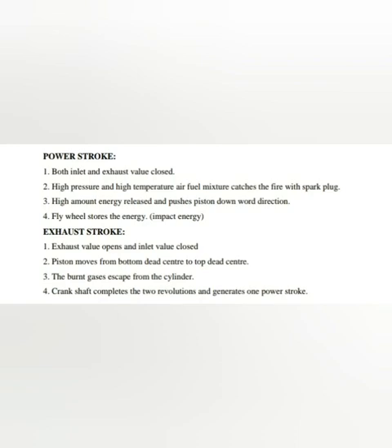The expansion of the gases is adiabatic in nature and is shown by the curve 4 to 5 on the PV diagram. Since the actual power or work is produced by the engine in this stroke, it is also called the power stroke or working stroke. Also, expansion of the gases occurs during this stroke, and hence the name expansion stroke.